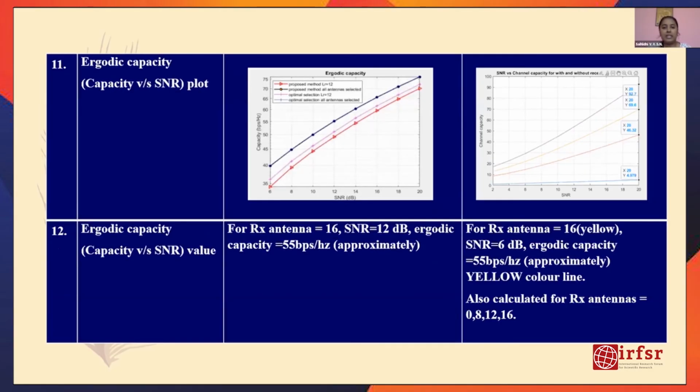Next, we have the capacity comparisons for both the papers. On the left, you have the signal capacity for LDPC encoded data. On the right, you can see the signal capacity for turbo encoded data. The basic capacity algorithm that I have used here is the ergodic capacity, and we can also have other capacity calculating algorithms such as the water filling algorithm and so on. So even for the capacity, you can see that we are getting a reasonable and effective capacity.